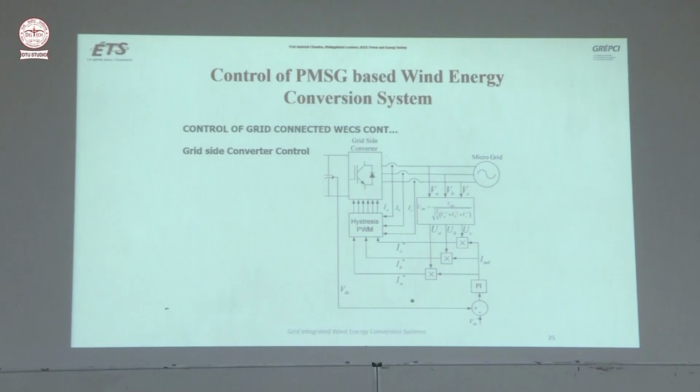And you can put it like this. Same thing as in active shunt filter, we are putting the same thing. You are measuring VA, VB, VC, calculating the unit vector for the voltage UA, UB, UC. You are measuring the 3 grid currents IA, IB, IC, and here you see you have measured VDC, you have reference VDC, PI controller.